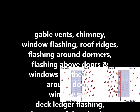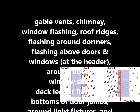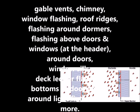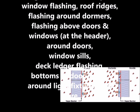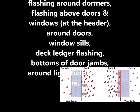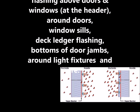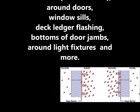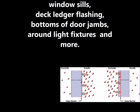Since moisture is also dissolved in air into water vapor, moisture also moves with air movement. The effects of wind on the exterior of the house are synergistic with the effects of moisture intrusion. They work in tandem with each other. Wind can drive water intrusion, but it can also have a drying effect if the relative humidity is different. Moist air can wet a house, and dry air can dry the house. But all of these effects interact with the hydric buffer capacity of the house.